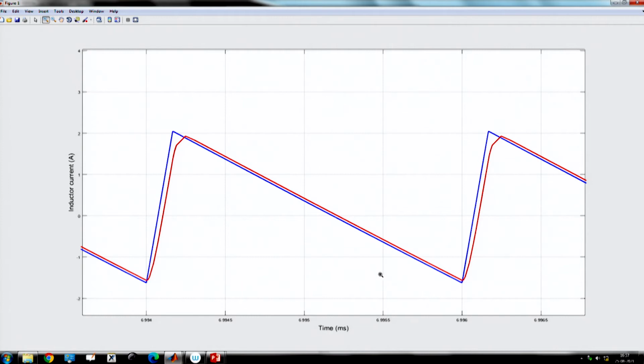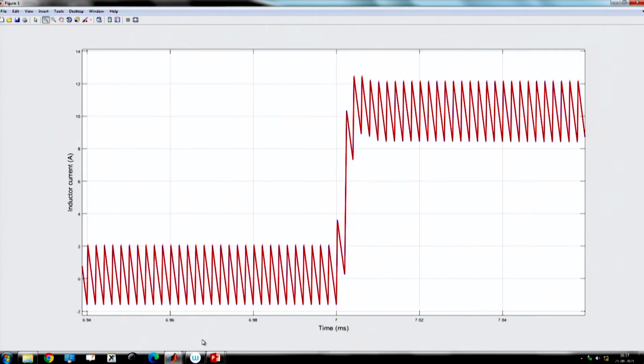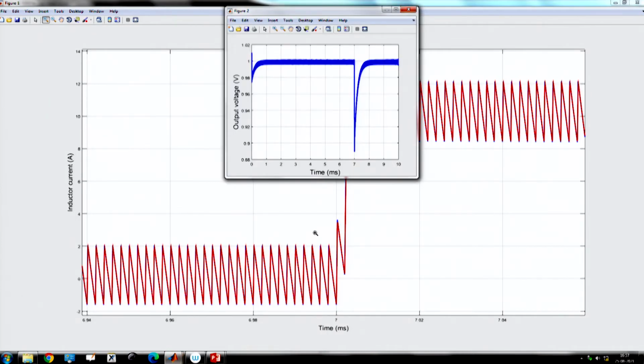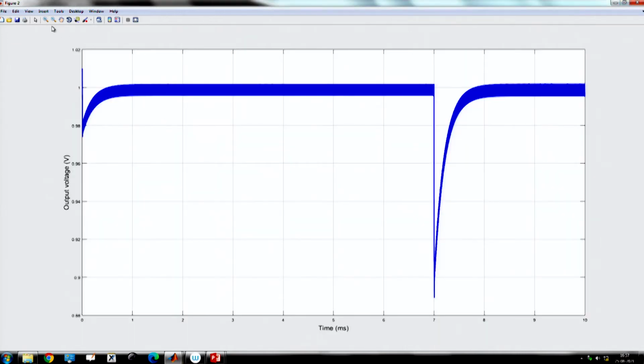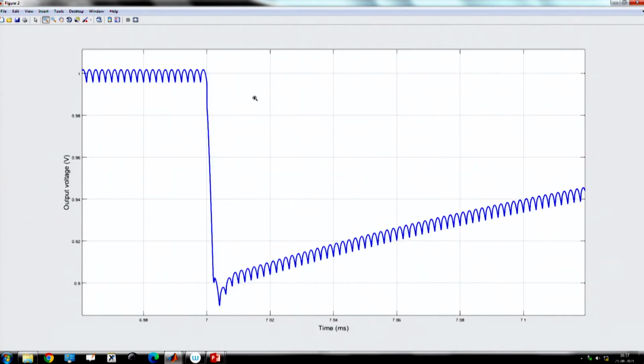As a result, it is somewhat smoother. So, you get close to the current waveform, but not exactly the same, and the response is pretty fast because we have a very high bandwidth current sensor. The transient response looks as usual for current mode control, a fast first order behavior that we can expect using this controller.